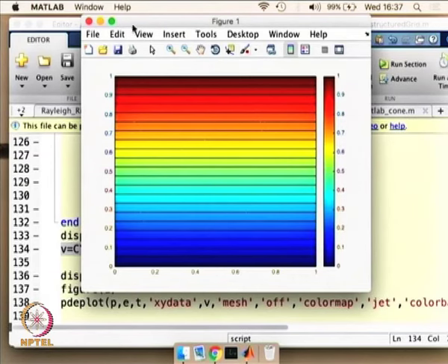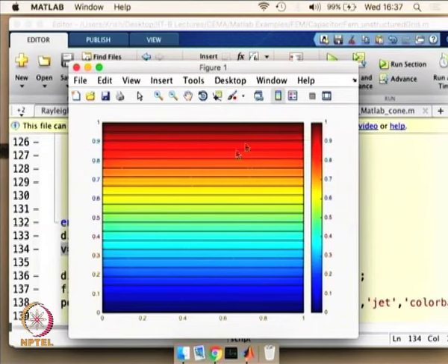We see that the potential on the top plate is 1, and on the bottom plate it is 0, and there is a natural linear gradation from the top plate to the bottom plate. There is an assumption on the left hand side and the right hand side. The assumption is that the fields follow a certain physical pattern, as if the plates are infinitely long in this direction and this direction. Assuming that the vertical direction is y and the horizontal direction is x, it assumes that the plates are infinitely long in the x direction.